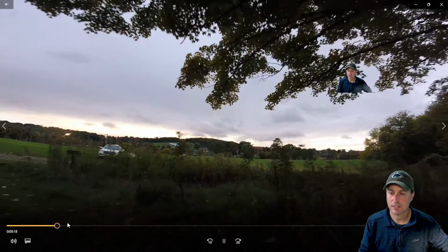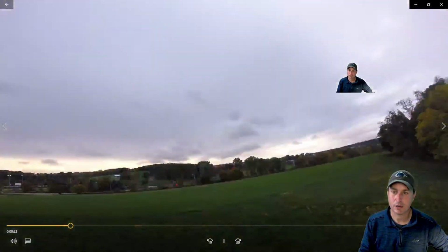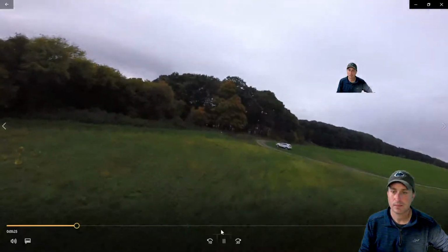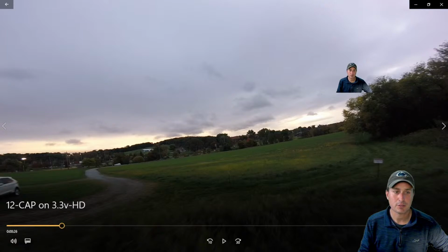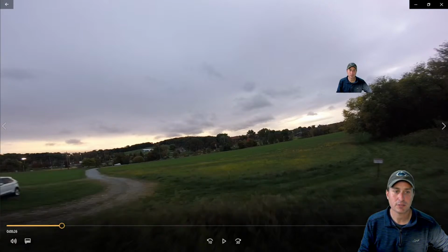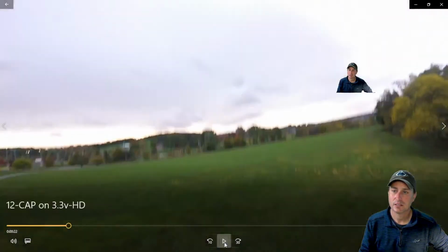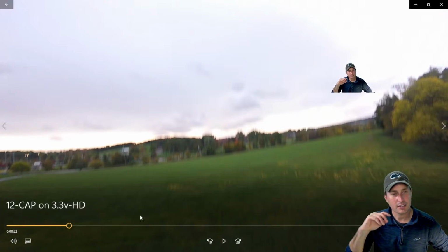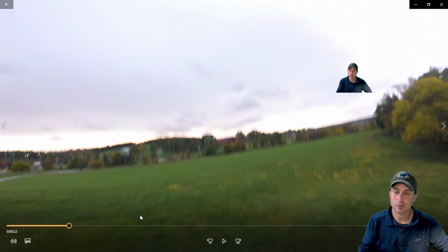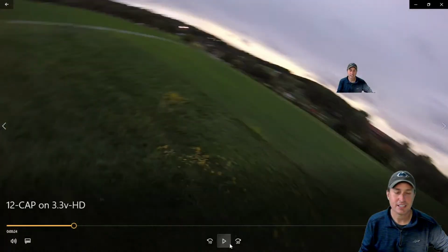You've got to let this catch up a little bit. See how it overshoots? See how in those first couple of pitch moves I was overshooting my rates? Let's play back through that. See how I was almost upside down again? You have your rates memorized for forward flips, and if you start to get that, obviously that's an easy telltale giveaway. And you can hear it.